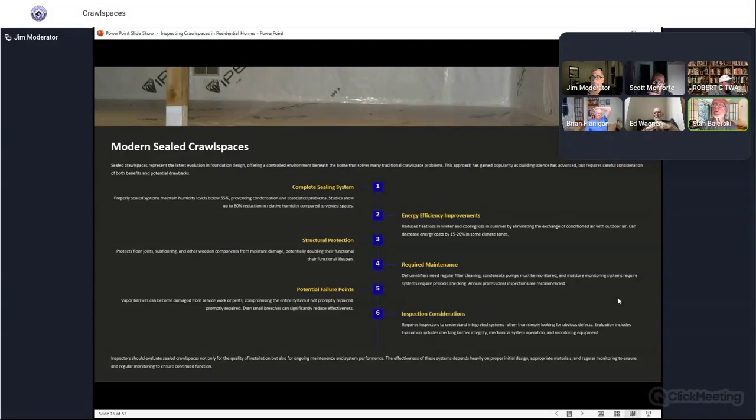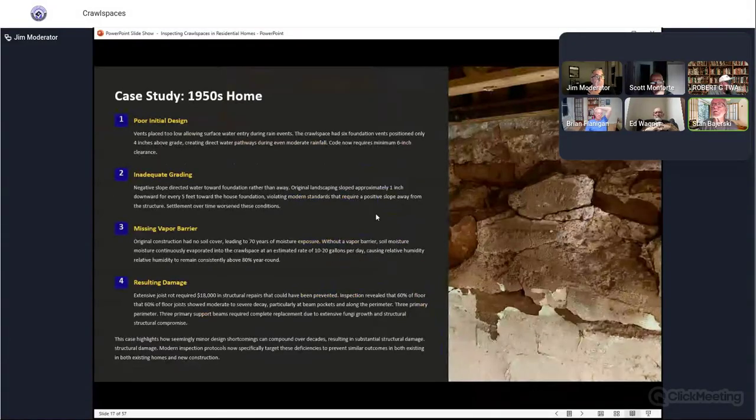If most of the wood is covered by vapor barrier, then we can't do an effective wood destroying insect inspection. I say we because I do my own. But even if you hire somebody and bring them along, they're not going to see too much of that wood. And how do we know what's going on behind all that barrier? I mean, we could have decay.